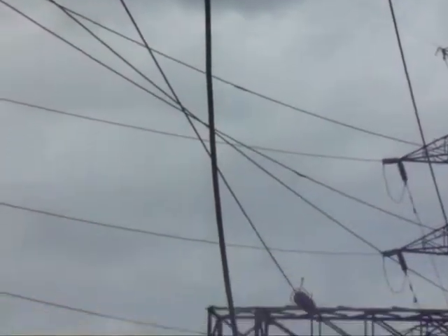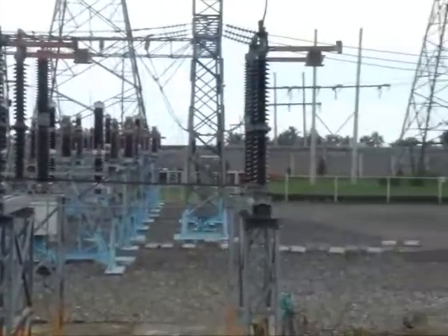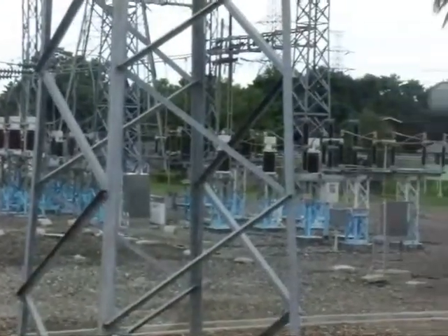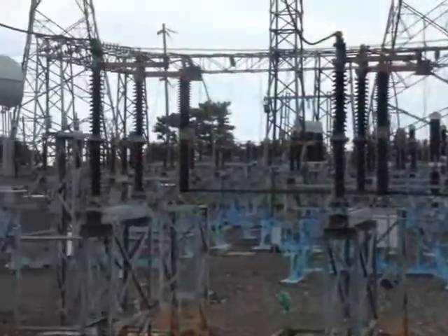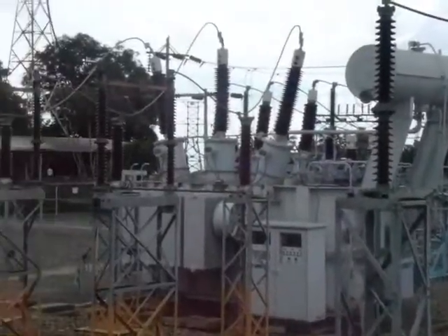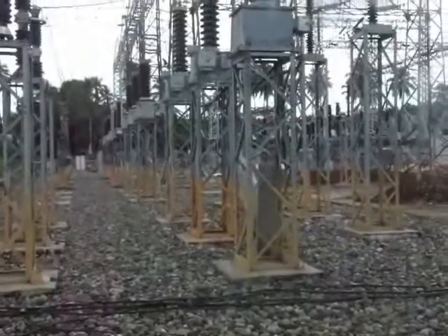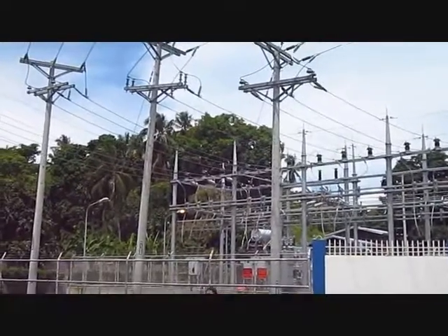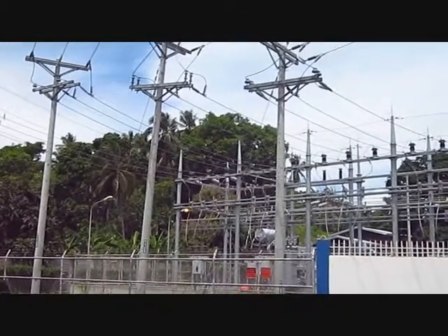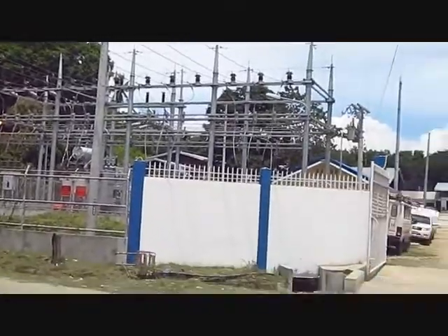At the primary substations, the voltage is stepped down to a value more suitable for the next part of the journey toward the load. Very large industrial customers may be served from the transmission system. The portion of the transmission system that connects the high voltage substations through step-down transformers to the distribution substations is called the subtransmission network. There is no clear delineation between transmission and subtransmission voltage levels.